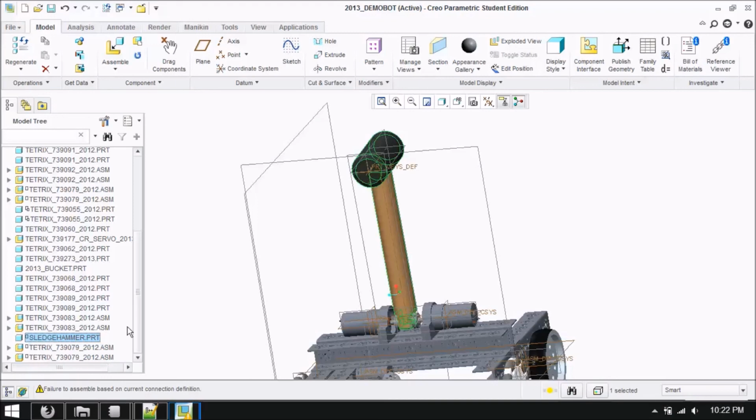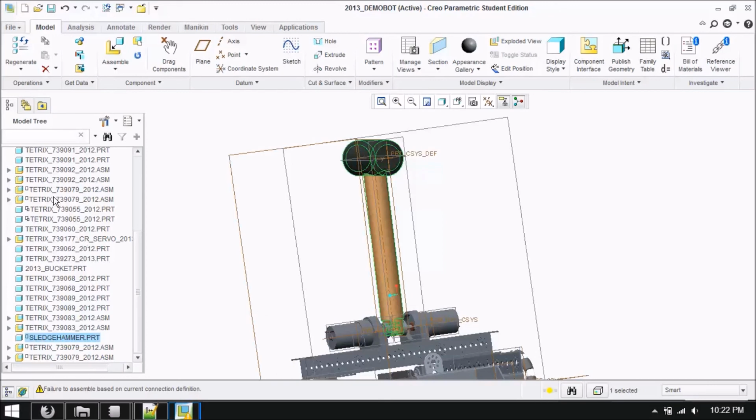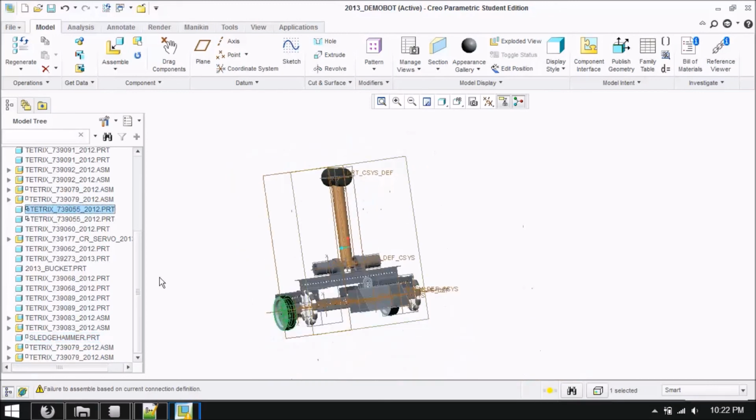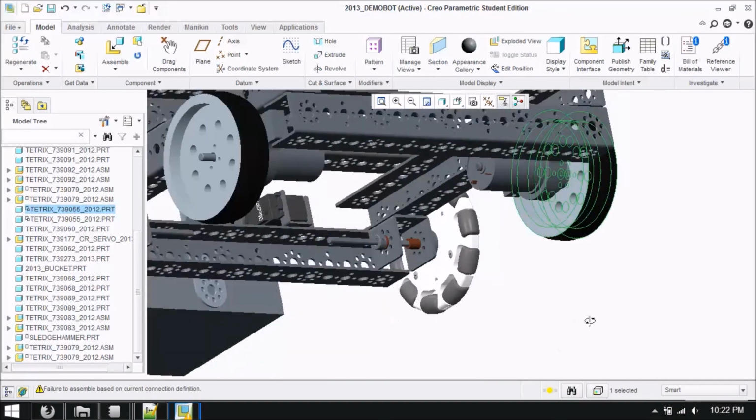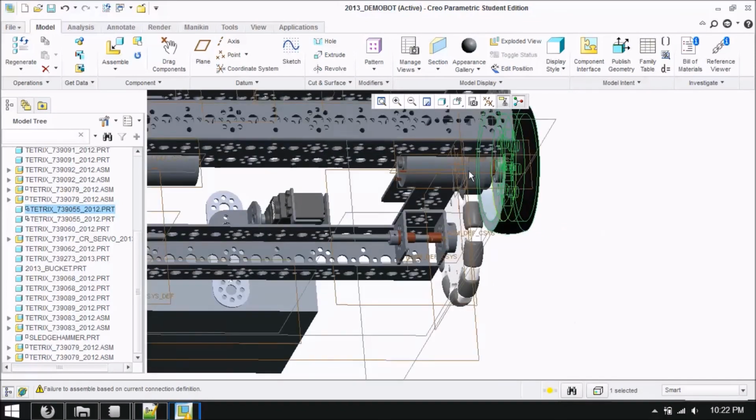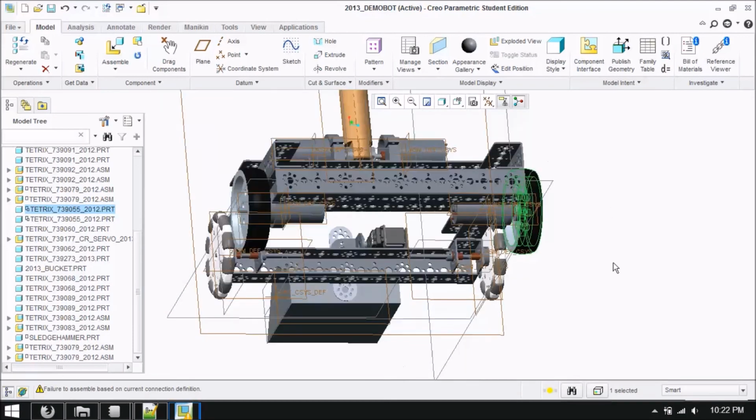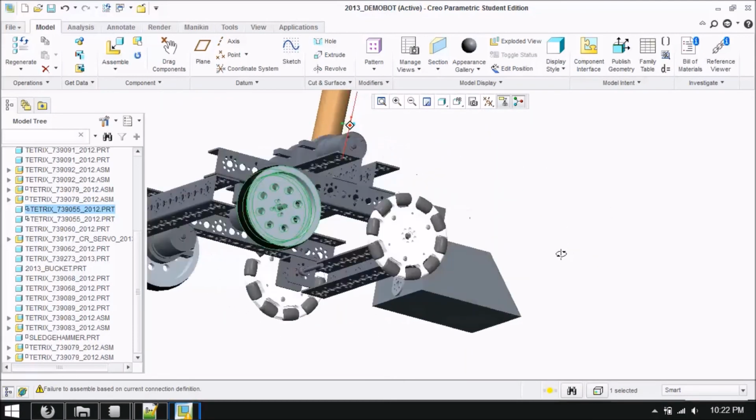And what that would mean is I've got an unconstrained object hooked up to a non-constrained object, which is obviously bad. The ideal thing is for everything on this side to be constrained. Actually, I got one here. This wheel is multiply unconstrained, and that's because I didn't hook it up to this bracket, right? Probably is the case with that.